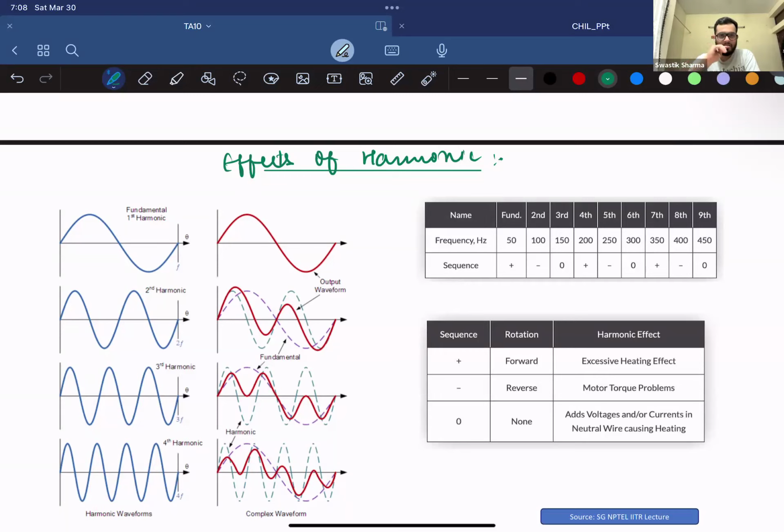But what if you get something out from some component and you check the output of that AC wave? What if it doesn't match perfectly to that AC wave? It's taking input from the AC grid only, so it should be producing an AC wave which is 50 hertz frequency with the same looking graph. But if it's not like that, what exactly is happening is that the waveform is plagued with harmonics.